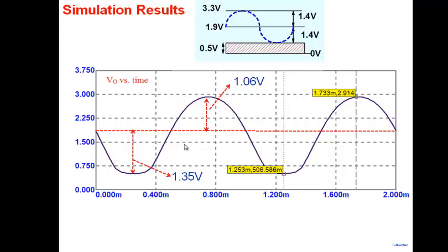More than that, the problem is not so much occurring here. The problem is occurring on the higher side. In fact, this is not bad. We were saying it can go up to 1.4. It's going up to 1.35. That's not bad. You are raising a valid point that my triode region begins once it enters this particular region, and my shaded region was calculated on the basis of a particular gate to source voltage.